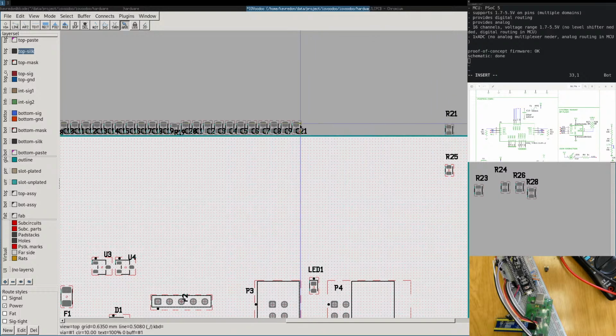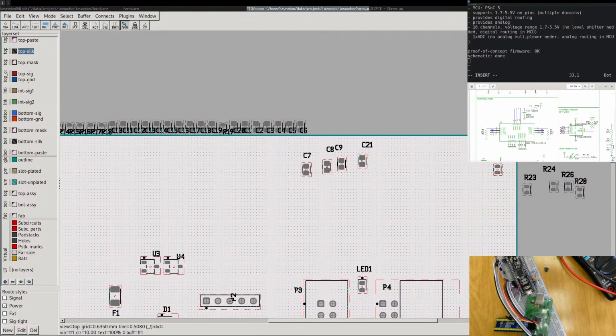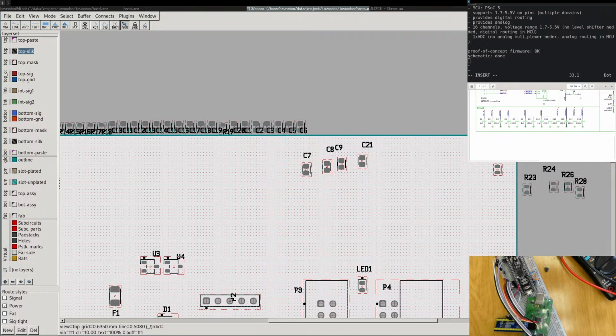They're all resistors, plenty of capacitors. The decoupling capacitors next to the pin. Although it is not shown in the schematic, I put all the capacitors here, but I know from the layout that these bypass capacitors need to go next to the corresponding lines.